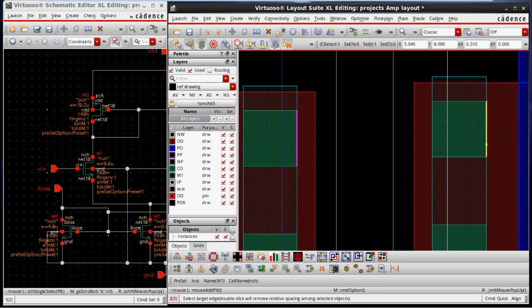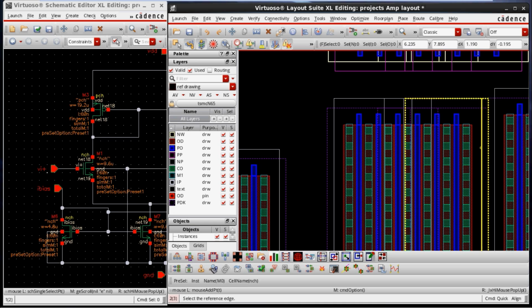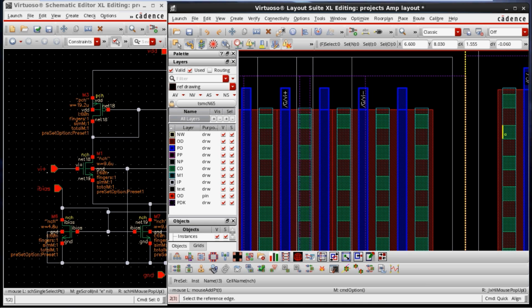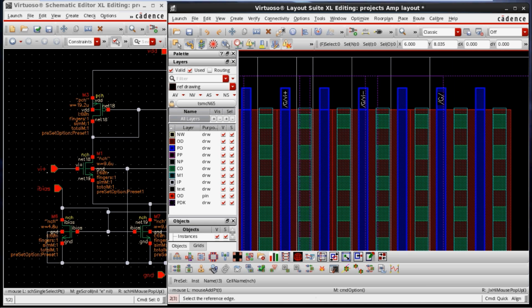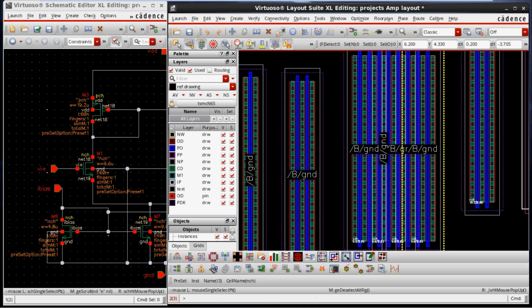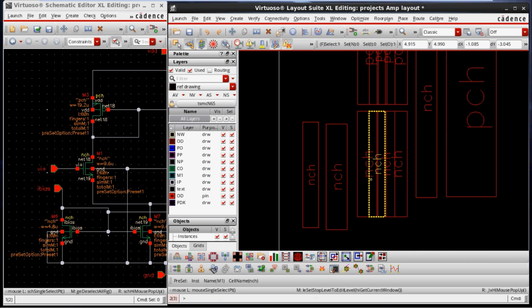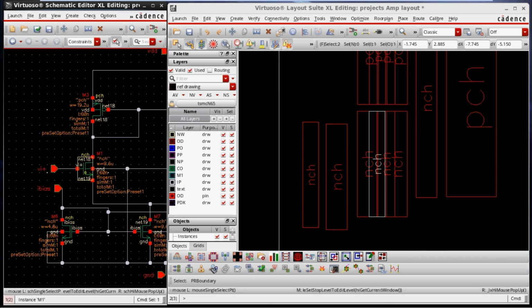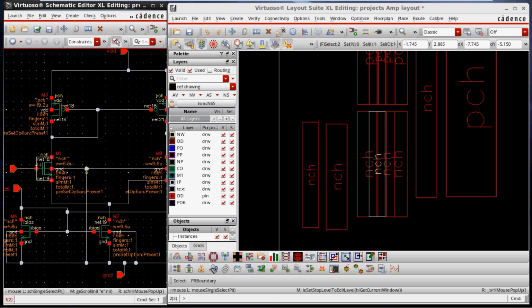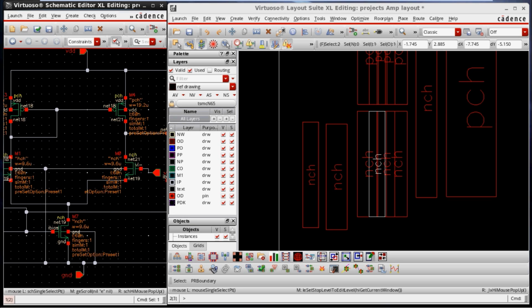So this dummy here, and then one more dummy we have on this side, right? So this dummy here. See, now I have added two dummies with the diff pair. One sec, you can clearly understand this. So we have these NCH, right? See, this is the first differential pair, which is highlighted with white color. The first diff pair, and the second diff pair is next to that.